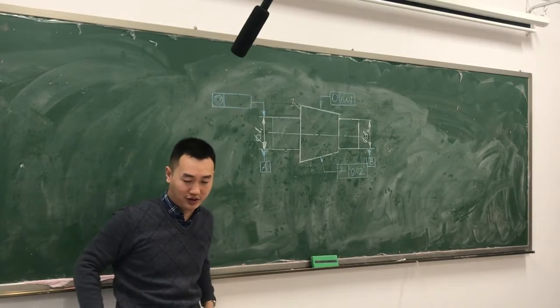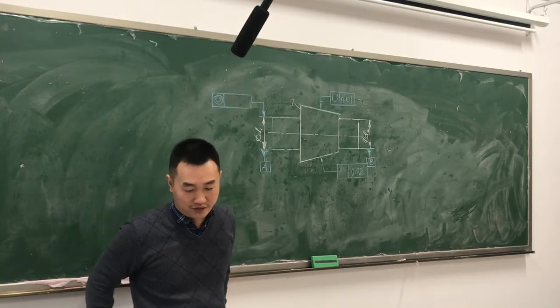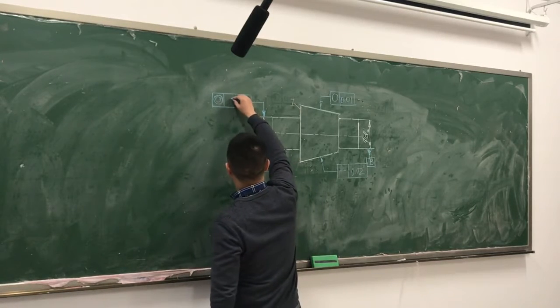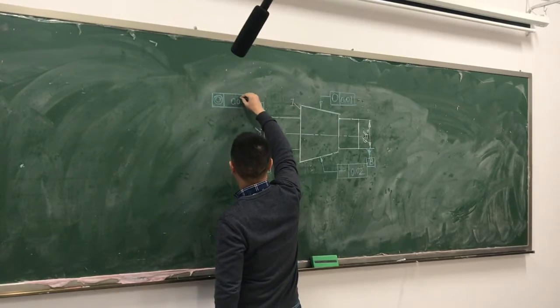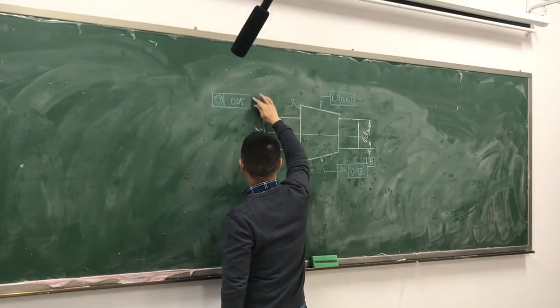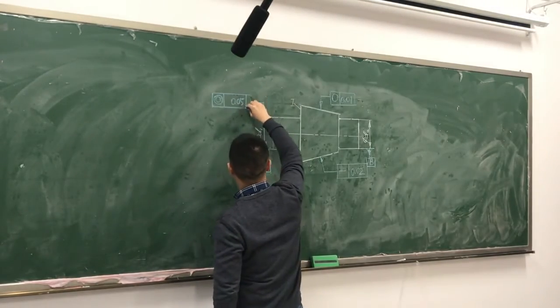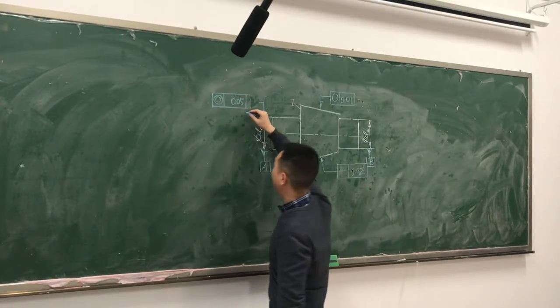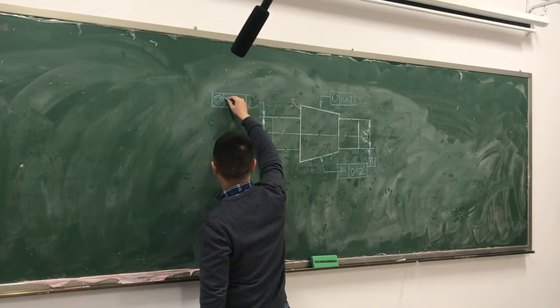And now I want you to think about it. Should we put a phi before this value, 0.05? Should I put phi before the tolerance value? Yes, right? Because what does the tolerance zone look like?